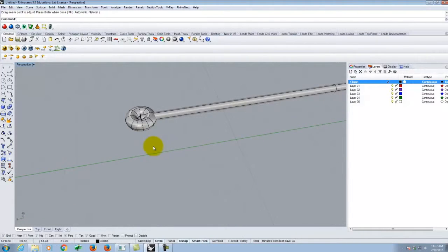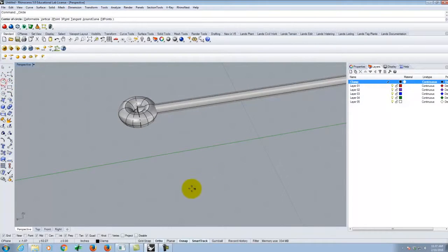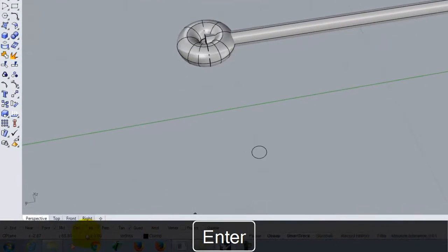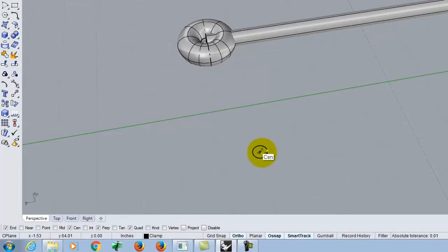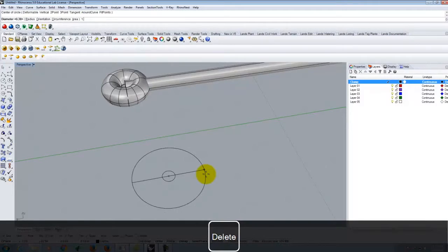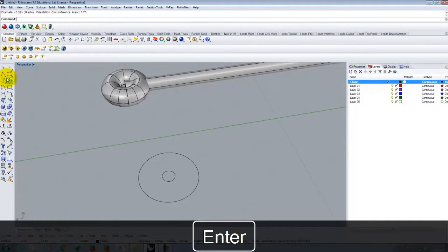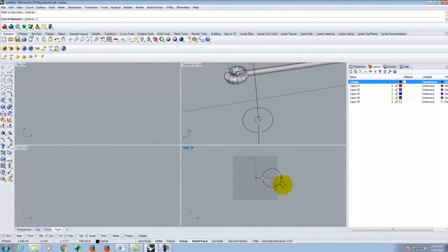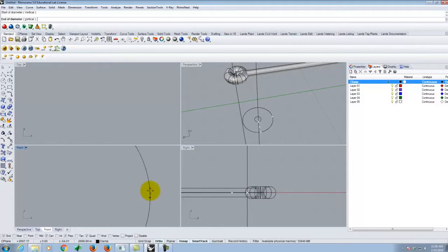If I were doing it, I would save a couple steps in that I would do my inside of 3/8. Let me turn on center snap here. Oh, come on. My outside would be 1.75. And when I did this diameter curve right here, I would actually do this in one of the side views, by referencing, whoops, it would be in the front view, my bad.